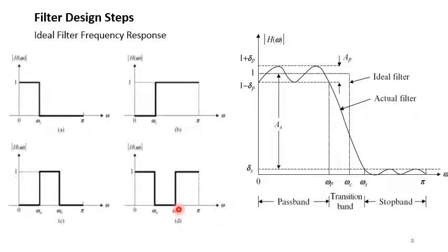Similarly, this is an example of the band stop filter. All those frequencies between the lower and upper frequencies will be suppressed by this filter. So if the input signal has frequencies from 0 to pi, then when we use this filter, the output of the system will have frequencies between 0 to WA and WB to pi, whereas in between these frequencies they will be stopped.